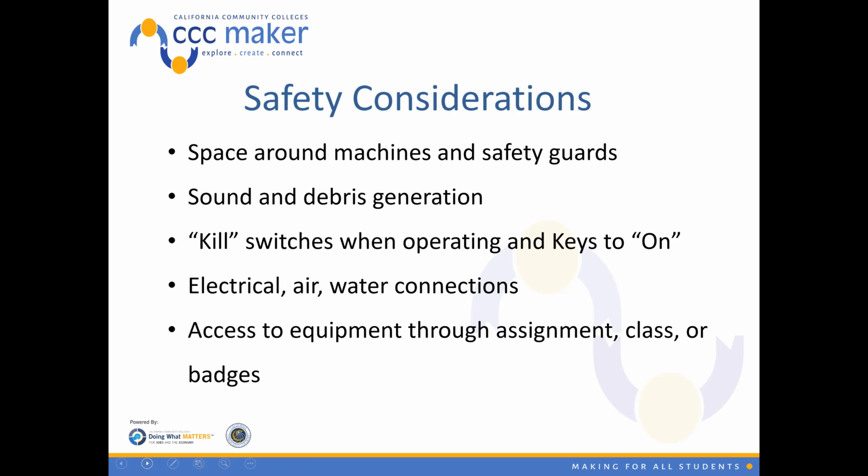Many of these machines, especially on the CNC end, do generate a lot of sound and debris. So you want to consider, how are you collecting the debris? How are you moving the debris across the machine or in the room? And is it going to generate a lot of sound? If you have a machine that's generating sound next to your workspace, you want to consider the fact that people may be working nearby.